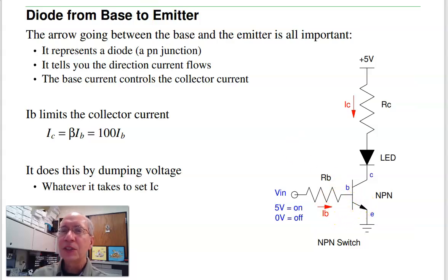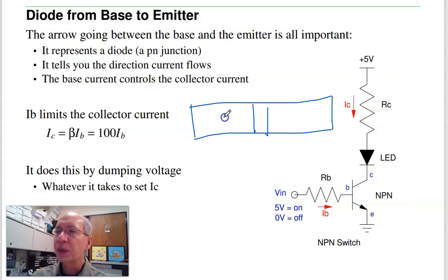What happens is a transistor is a current amplifier. Kind of the way it works is an NPN transistor has got three regions, N, P, and N. This is your emitter, base, collector. Now normally there's no current flow, emitter to collector, no current through the LED, because this is a reverse bias diode in there. I can turn that on and off with the base. So if I apply a little bit of current at the base, these are going to be holes in the P region, flowing P to N. If holes are flowing P to N, I've got electrons flowing N to P. Now the base is really, really thin, so those electrons shoot right through.